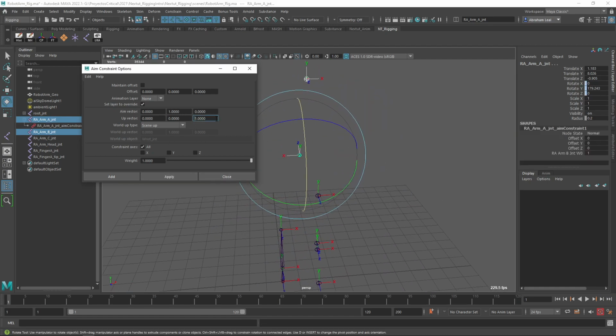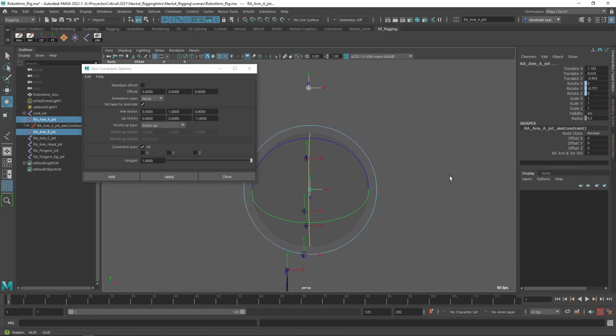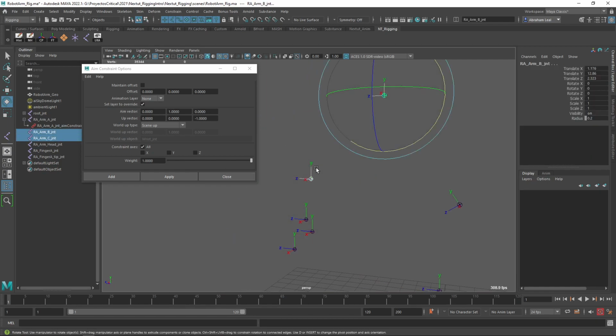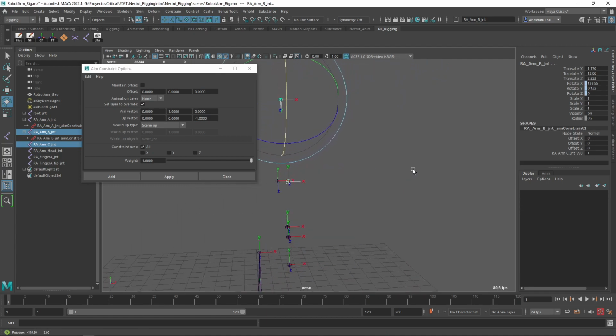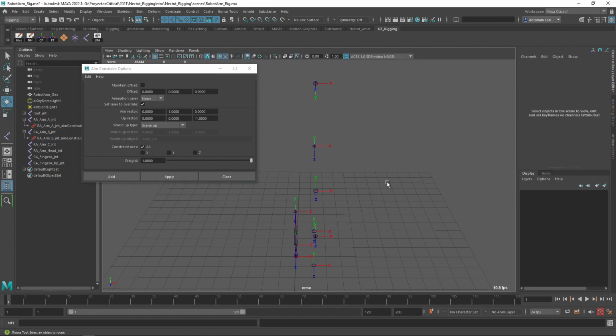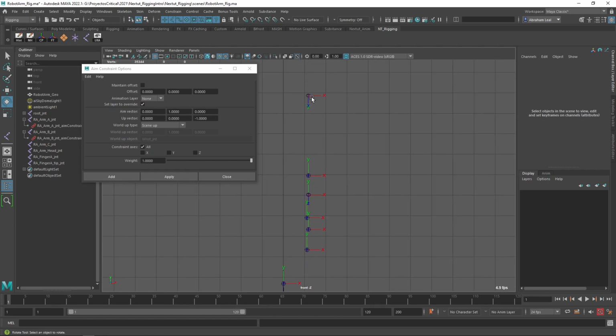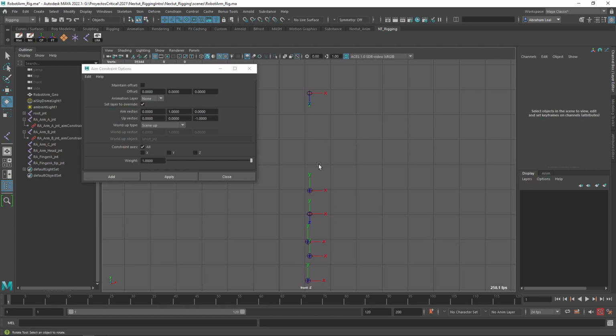That's a little bit close. But what I'm going to do here is say -C. So that way the x-axis, as you can see, is now properly pointing to the x-axis. Perfect. So same deal here. 1, 2, driven. We're pointing with the y-axis and we're using -C. So we're pointing the C towards the floor. And we're going to hit apply. And as you can see, now everything is aligned properly. I'm also seeing that things are not completely aligned here. Like, see how each of them are in a different position? That shouldn't be the case, but it's not making it difficult, so we're just going to keep going.